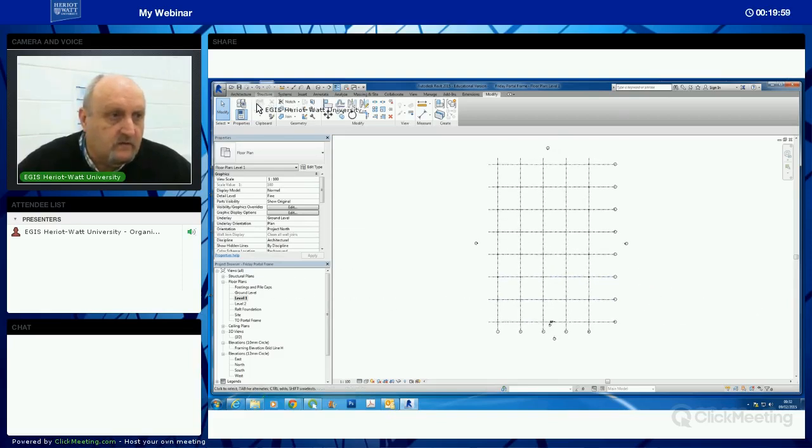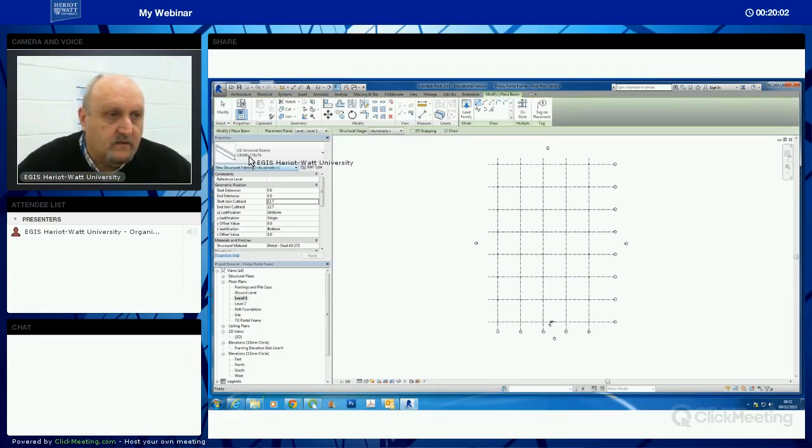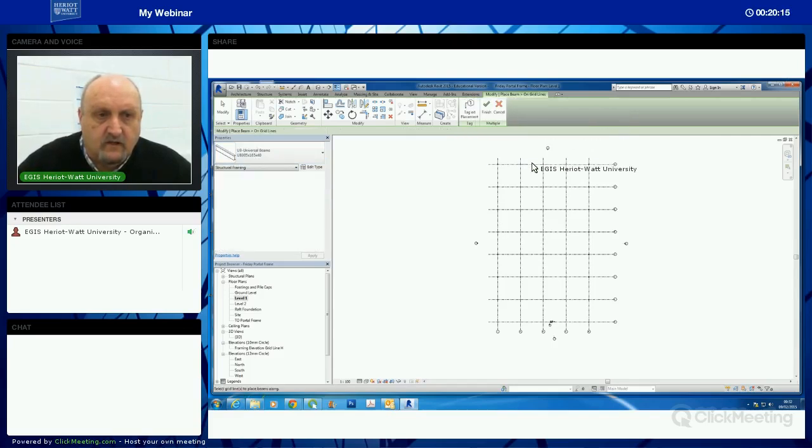I'm going to put in the beams on level 1. So level 1 structure beam. This is still the kind of heavier gauge beam that I used for the portal frame, so I'm going to throttle it down a wee bit. 305 by 165 by 40 is fine. This tool here is the grid tool, and if you carefully hold the control key down, you'll see that these beams are going to be inserted along that grid line all the way down. And then same with these along here.